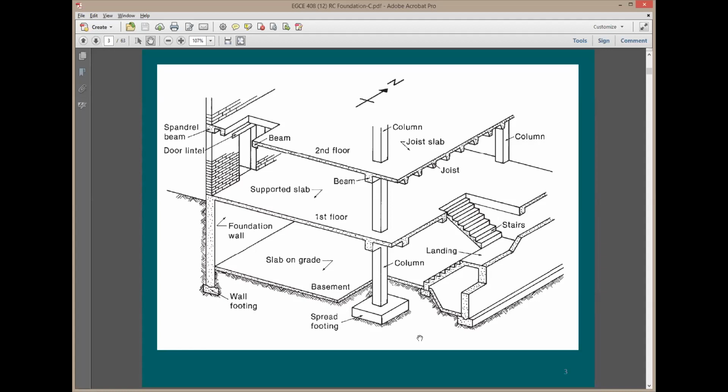And with that, you're going to have the actual soil pressure. Now, you want to be sure that this actual soil pressure is within the level determined by the soils report or geotechnical report. What happens if you go beyond the allowable soil bearing pressure? More settlement is going to happen, excessive settlement, which you don't like. No one likes this.